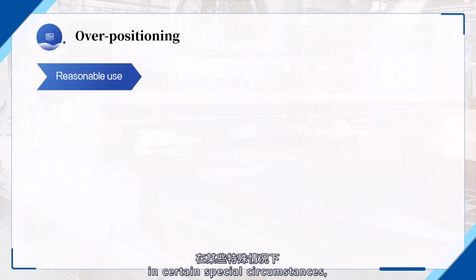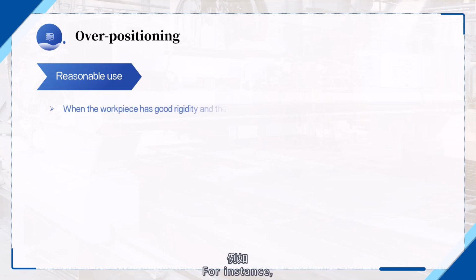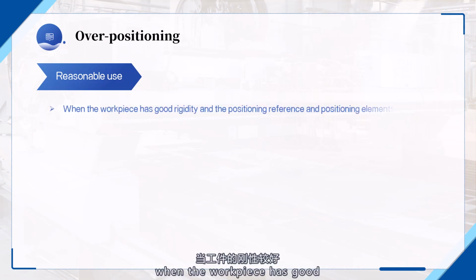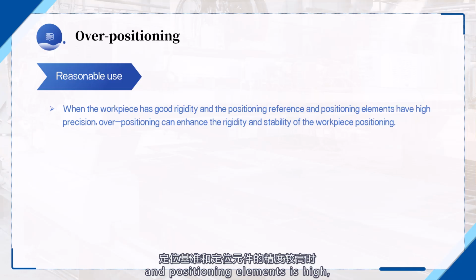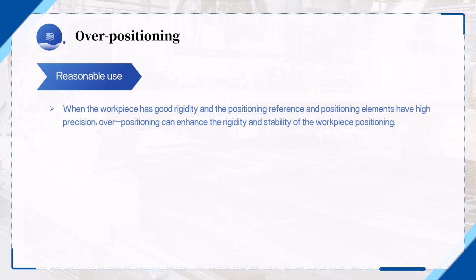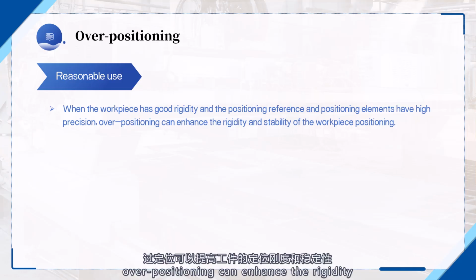However, in certain special circumstances, over-positioning can be reasonably utilized. For instance, when the workpiece has good rigidity and the precision of the reference points and positioning elements is high, over-positioning can enhance the rigidity and the stability of the workpiece positioning.